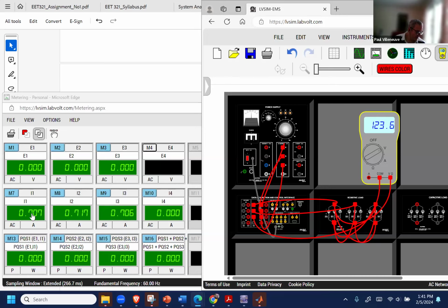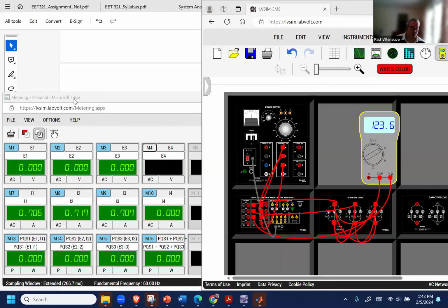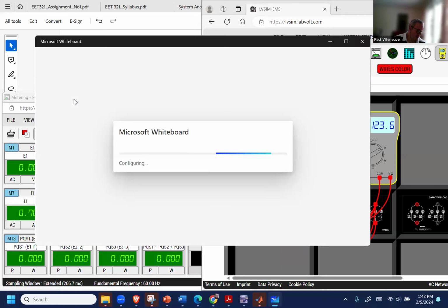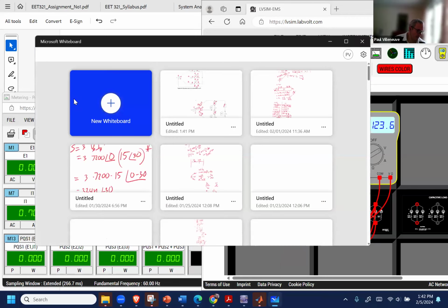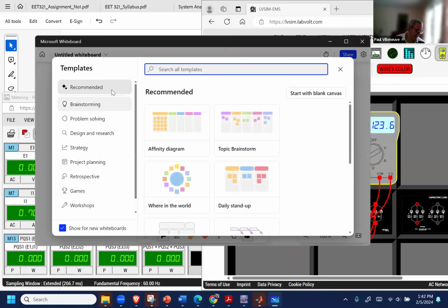How does this current here, the 0.707, compare to the current that we had in the previous circuit? It's pretty much the square root of 3. Yeah, it's the square root of 3 difference. So in a delta, what we see is that the phase current is square root of 3 different than the current that's into the line. And it's exactly what we'd expect it to be. So it's almost exactly square root of 3.